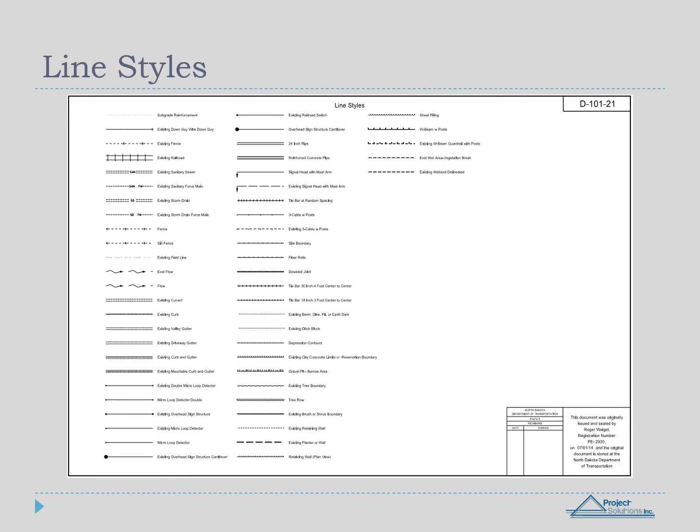In addition to abbreviations, line styles are also used to reference items on plans. Lines are often used to represent different fence types, road types, and utility types. This eliminates the need for labeling of a line, since the line itself can be used to deliver the information. However, we can run into an issue here.